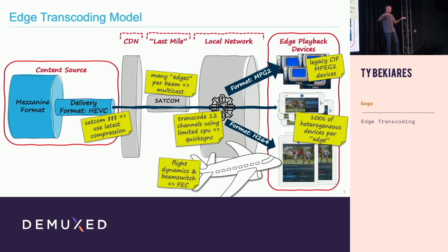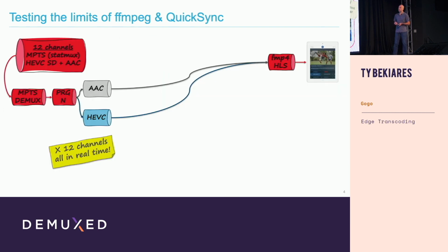Depending on the polarity and frequency and orbital position, you might be looking at signal loss on the order of a couple seconds to maybe like 10 seconds. So we knew that that would be totally unacceptable for a TV viewing experience. And so we employed a very large window FEC solution that could cover tens of seconds of loss of video over some minutes of time, such that we would never have any interruption regardless of whether or not we lost lock with the satellite. So at this point, we had proved to ourselves that HEVC is viable.